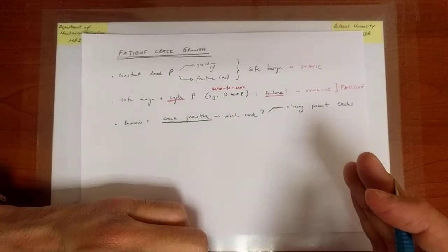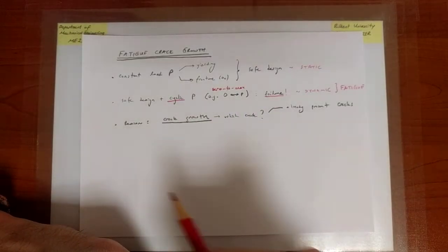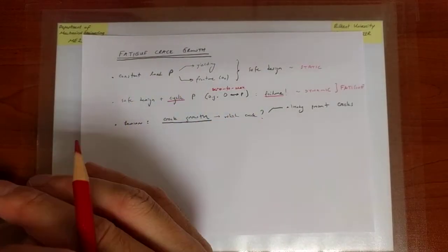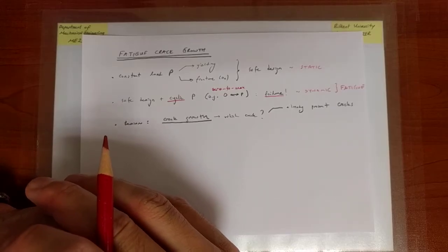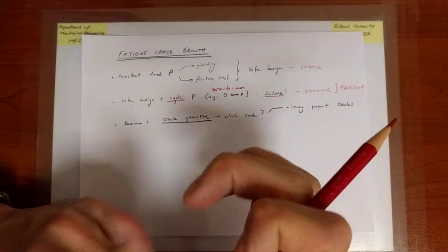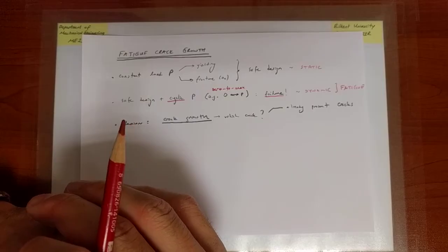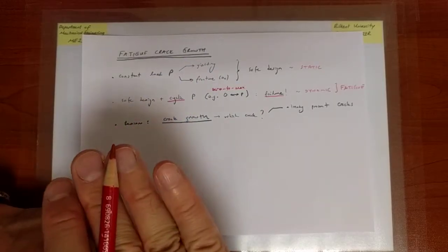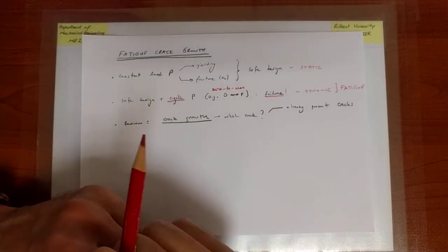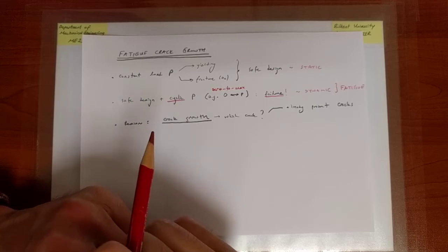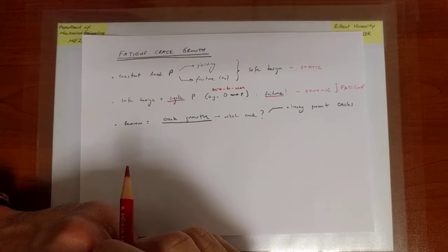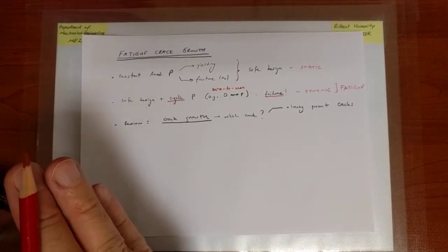So sometimes, for instance, you are manufacturing the crankshaft of a car. What is done regularly is that people check the surface of the critical portions of the crankshaft, where it connects to the pistons, where the surface has to be very smooth. And eventually they do an inspection. There are different ways of inspection. One of them is a manual, visual inspection. And if they see a crack, and this looks like a non-standard scenario, they immediately discard the piece.